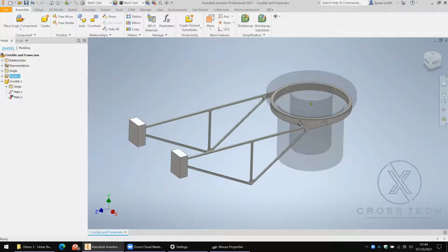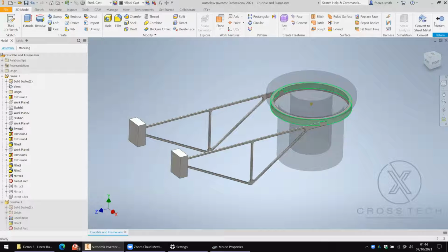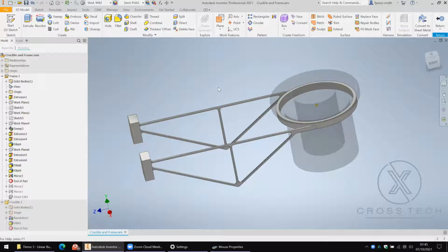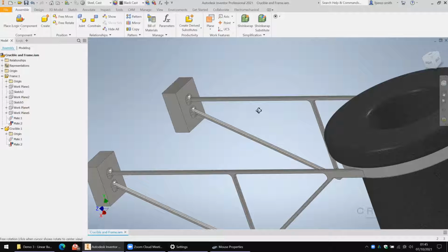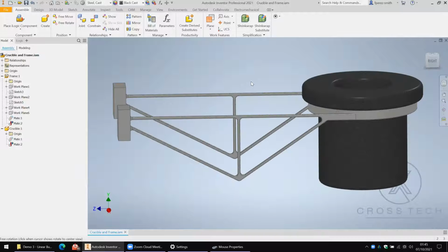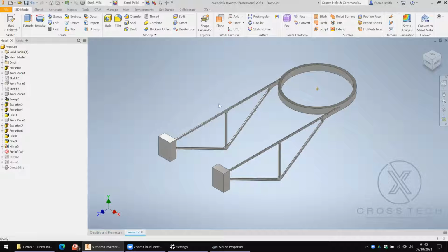So what we want to know is, will it yield? But say that somebody's already done the analysis, and I know it doesn't look it, but it's within the strength of the material to not yield. It bows a little bit because there's quite a bit of deflection because it's a bit skinny, but can it fail in any other way? If anyone's done a few analyses in the past, you might say, okay, something doesn't yield, but that doesn't mean it's okay. In this case, it might be subject to buckling. That is to say, it might literally kink in on itself and fail by rapid buckling.